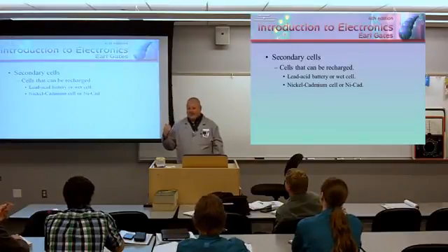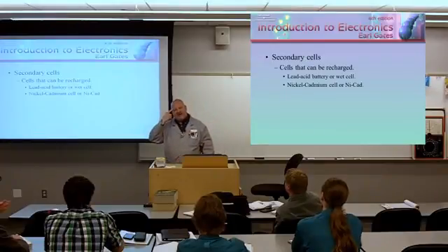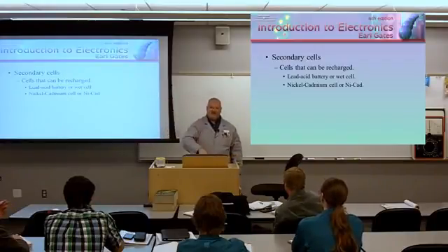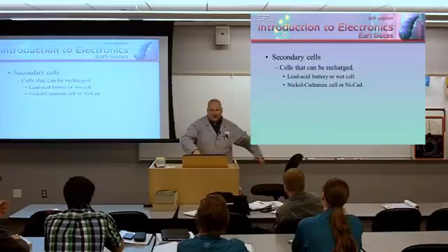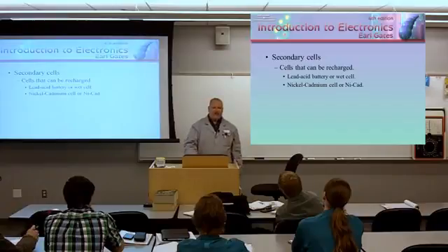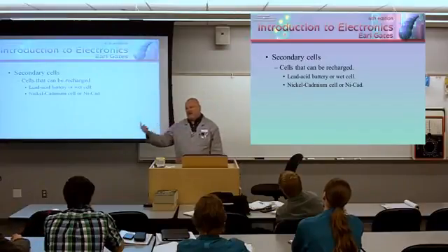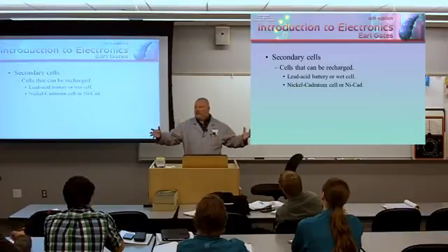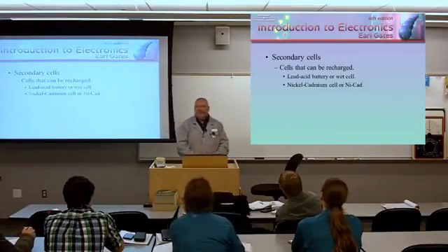They lose the power at that facility, guess what? The whole northwestern United States, aircraft are flying blind. So they were kind of smart about this. They put in a battery backup system. As soon as the AC power crashes, these batteries have power inverters, and that brings it back online so they don't miss a beat. Once the batteries are online, they have diesel generators in another building on the property that will kick in, and they have huge fuel tanks so that they can power that for a very long period of time.